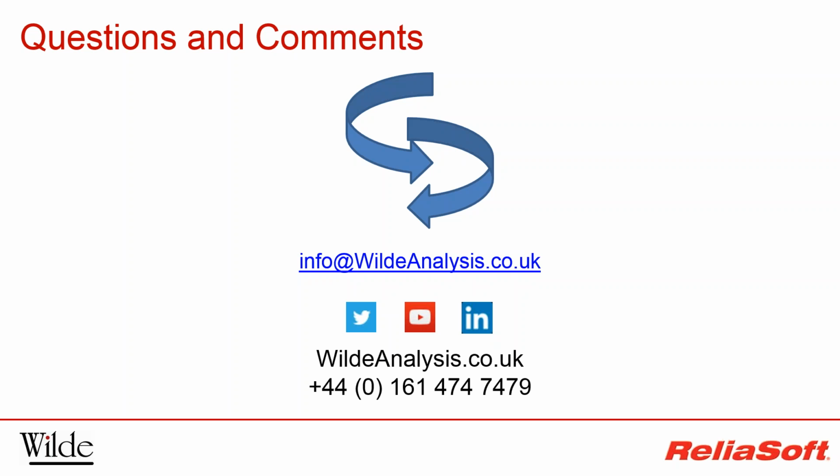Which standard is best for starting out when setting up an FMEA? There's a wide range of standards, and a lot of them are very industry specific, so it would be difficult to recommend one single standard to start out from, as this will depend on the nature of the product and the industry. But a particularly useful one is the British standard EN 60812, which was updated in 2006, I believe. It gives a very good overview of the top level of the procedure, much like I've shown in this webinar today, and just highlights some of the decisions that need to be made, gives some guidance on them, and also points towards other standards for more information.